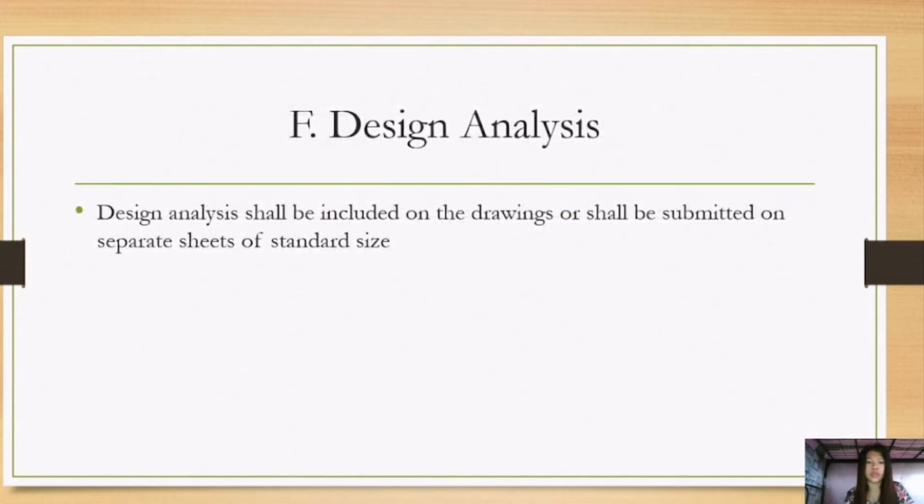Next is design analysis. So, design analysis shall be included on the drawings or shall be submitted on separate sheets of standard size because it is all about detailed calculations of short circuit current for determining the interrupting capacity of overcurrent protection device for residential, commercial, and industrial establishment and calculation of voltage drops.